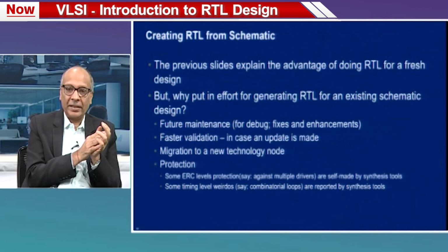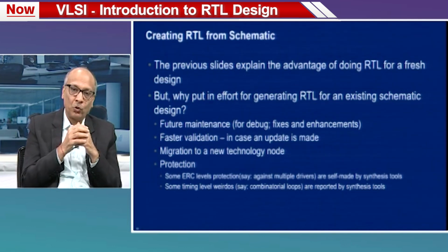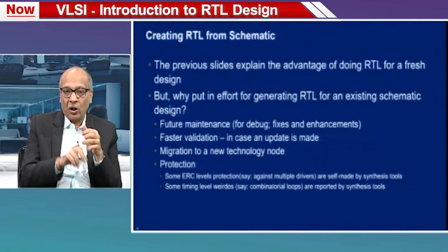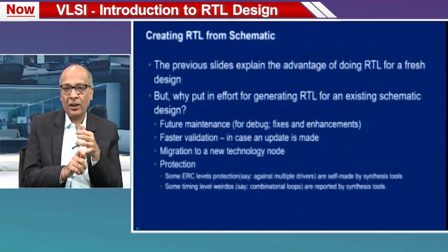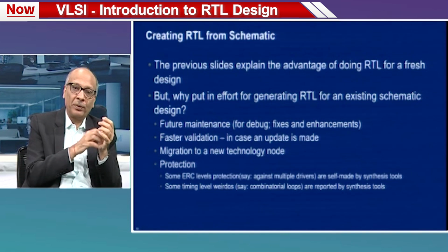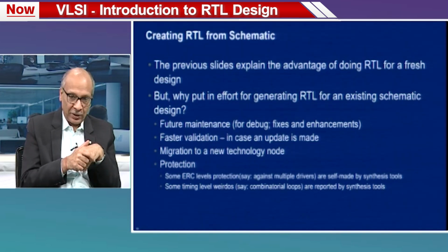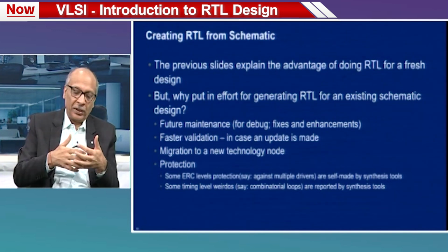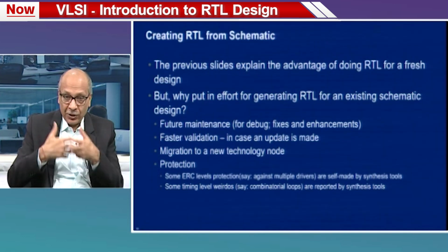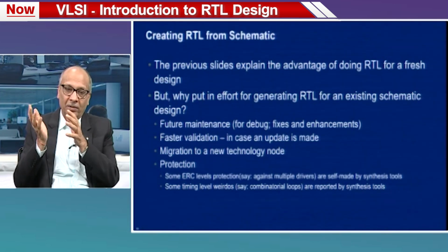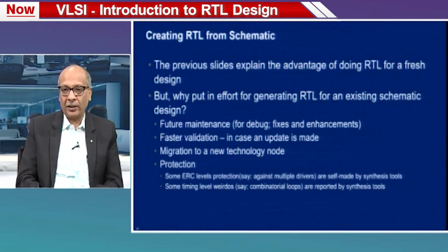The answer is yes, if the design is supposed to live for a longer time. Okay. Because for future maintenance, if you want to make future enhancements, some fixes, some debug, the RTL based design will be easy, while the schematic based design will not be easy. If the design is all done, dusted, you are not going to touch it ever, then let it be. But if you think that you will be updating this design, you have to maintain this design for long, then you should consider migrating it into HDL or RTL.